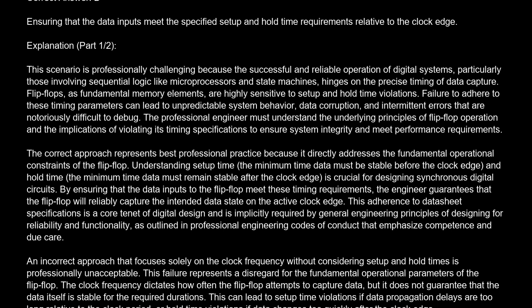Explanation. This scenario is professionally challenging because the successful and reliable operation of digital systems, particularly those involving sequential logic like microprocessors and state machines, hinges on the precise timing of data capture. Flip-flops, as fundamental memory elements, are highly sensitive to setup and hold time violations. Failure to adhere to these timing parameters can lead to unpredictable system behavior, data corruption, and intermittent errors that are notoriously difficult to debug. The professional engineer must understand the underlying principles of flip-flop operation and the implications of violating its timing specifications to ensure system integrity and meet performance requirements.